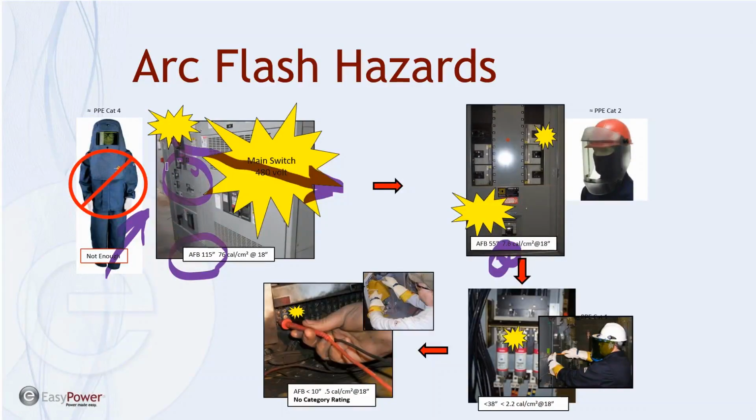In the 2018 NFPA 70E, it did state that rubber gloves with leather protectors are adequate protection for arc flash, which is a good thing. It didn't state what their ratings are, but they do exceed 40 calories typically, so they're able to just make that statement based on tests that have been done.